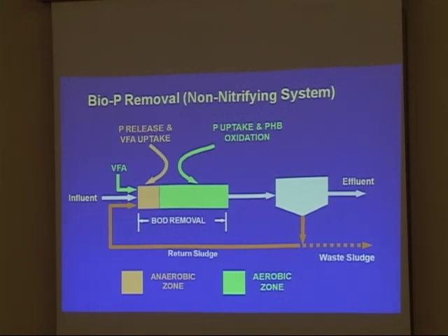Other situations, this is totally a different area, but like sulfur compounds, odorous compounds taken up in odor control, where it's scrubbed and captured into a liquid where it's oxidized. But that oxidized sulfur compound from hydrogen sulfide turns into a sulfate. If those side streams from scrubbers from odor control get into an anaerobic condition, you can get a re-release. You end up having hydrogen sulfide re-released again. So once you capture something, either in the case of a microorganism or by oxidizing it, you've got to make sure you don't put it into a situation where it's anaerobic, because you get a re-release of what you've worked so hard to get to begin with.